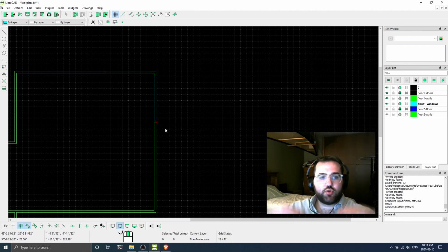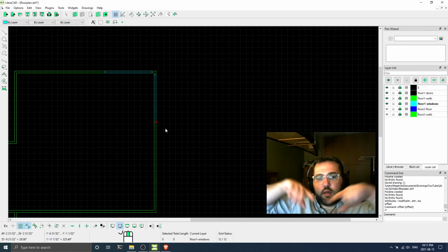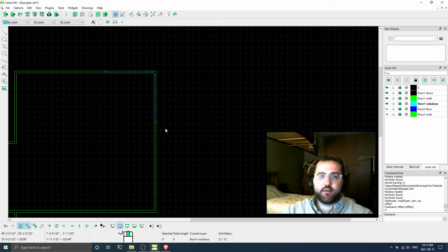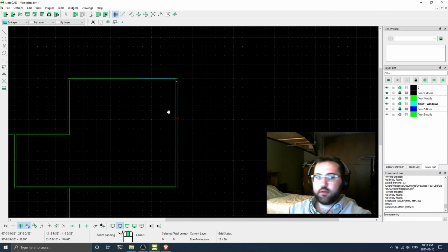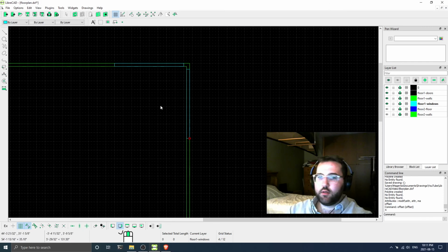That way you could extrude it vertically up to the bottom level of where the windows would be, and then draw in the voids around the window boxes. But for now I'm just going to leave that as it is and have this object appear above my walls layer so that I can actually see and distinguish it.